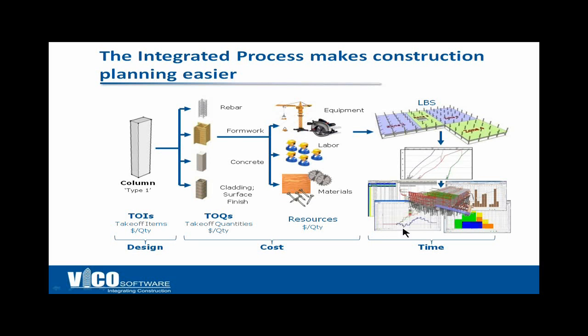And then all of these other reports that you see down here, including this 4D animation, are automatically generated. There is nothing to do to create them. This report is cash flow. This report is resource loading. I believe this is a concrete resource report. So a fully cost-loaded schedule is an output of the natural 5D planning process. And again, owners love that because they're always asking for cost-loaded schedules.